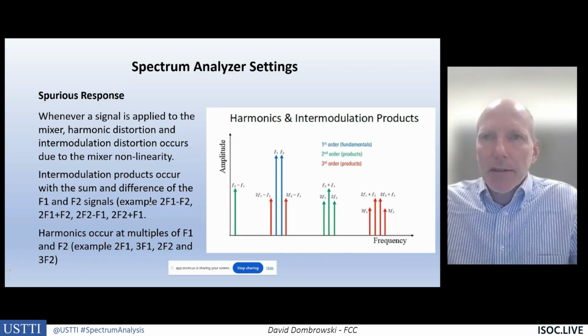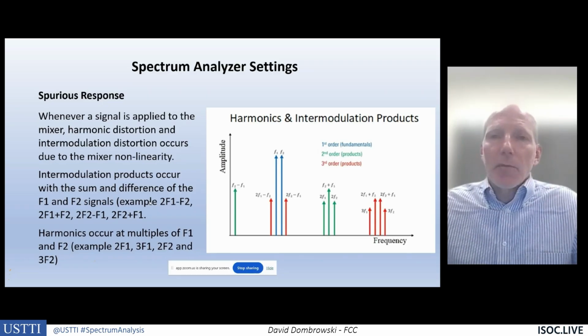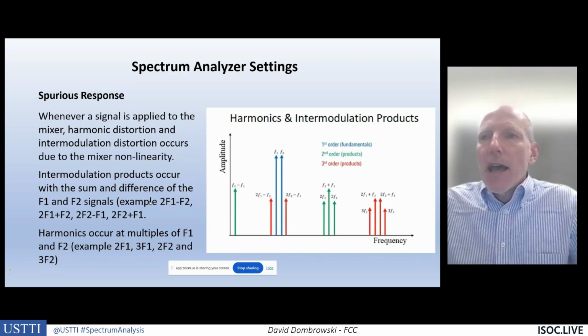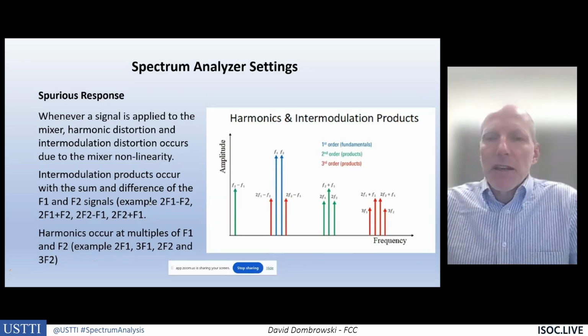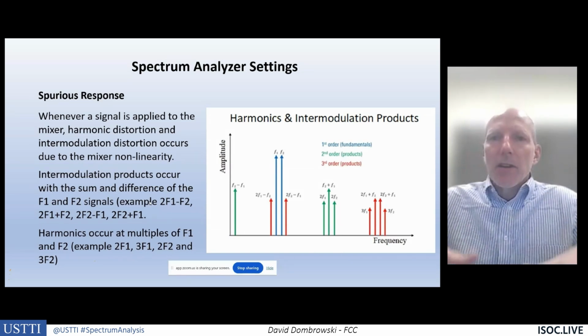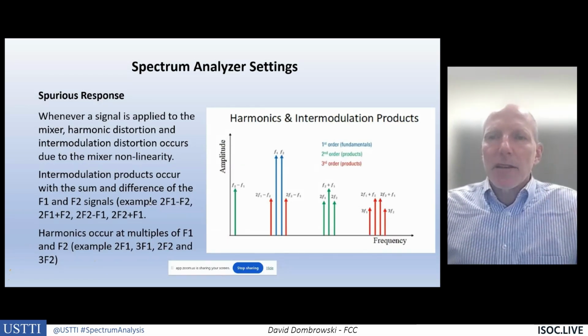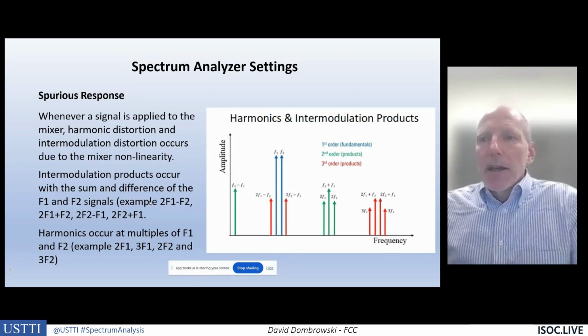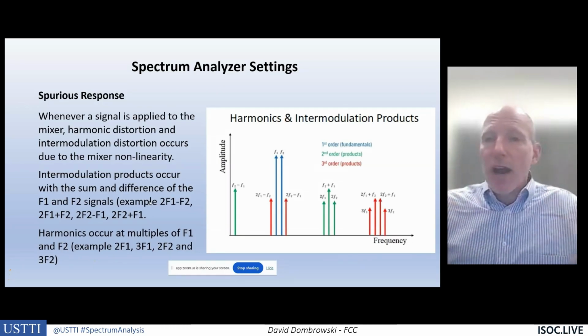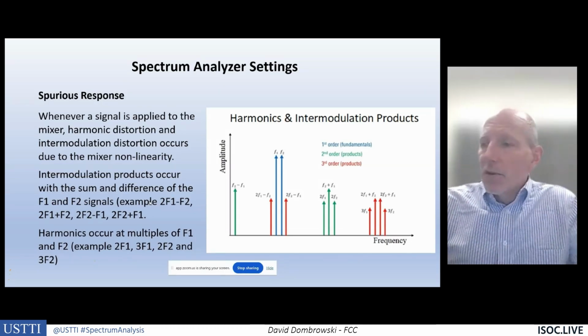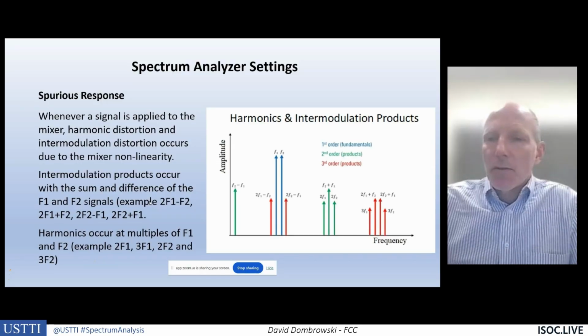We've seen this happen. We go up to tower sites. Those signals are very strong because we're right at the tower site. What happens is you overdrive your receiver, you overdrive your spectrum analyzer, and we start to see intermodulation products. The entire noise floor goes up. We start to see frequencies present that really are not there. You may drive yourself crazy trying to track those signals, and really they're generated in your analyzer.